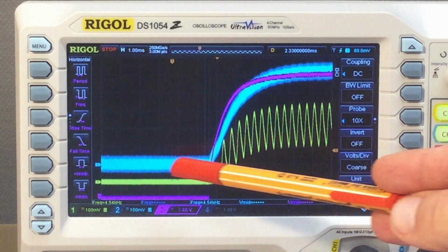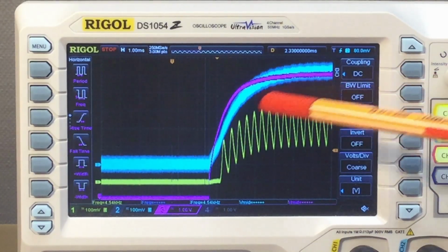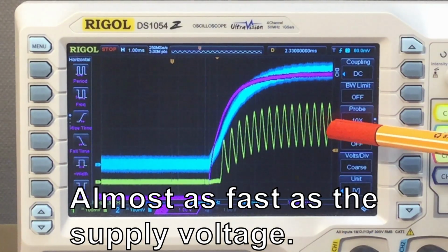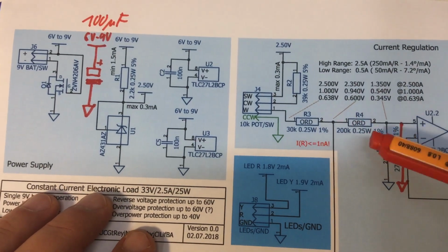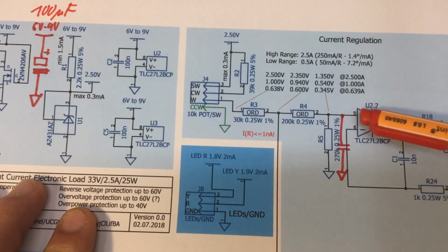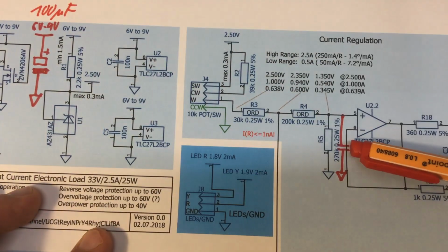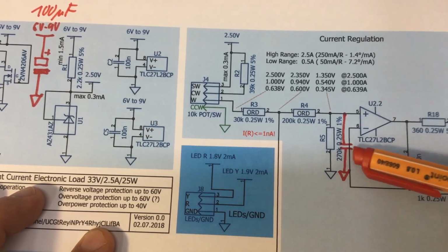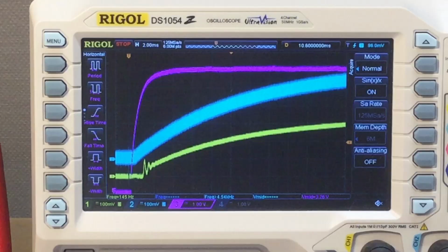But the positive input of our op amp is still ramping up a little bit too steep, so our current again starts oscillating. So let's go up with that capacitor here, which is smoothing out the positive input, from what we're currently at, 10 nanofarads, to let's say 100 nano, and let's try the whole thing again.